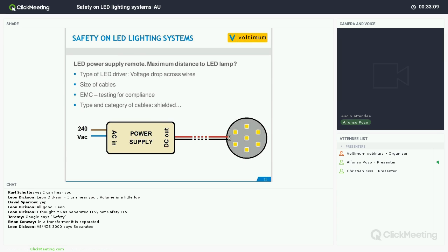In the case of constant current drivers, the LED module does not suffer the impact of voltage drop, but the driver might operate at higher stress, increasing the output voltage to counteract the losses in the longer wire. That might increase the operating temperature and might also cause some issues on the LED driver.